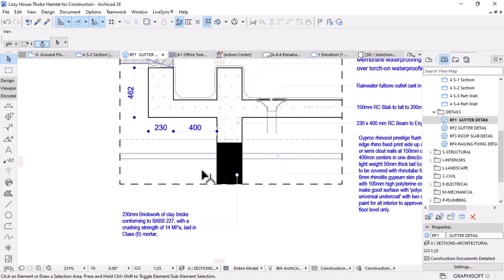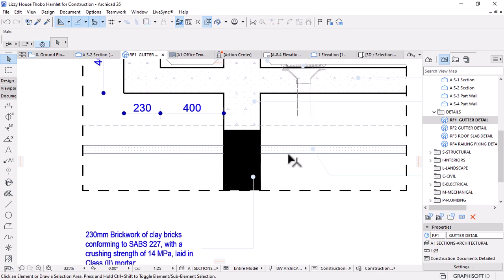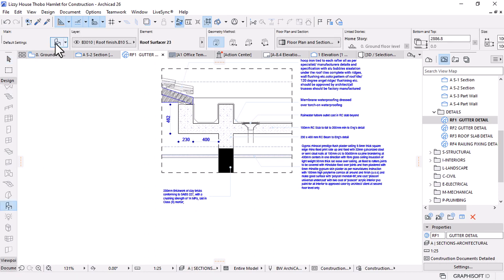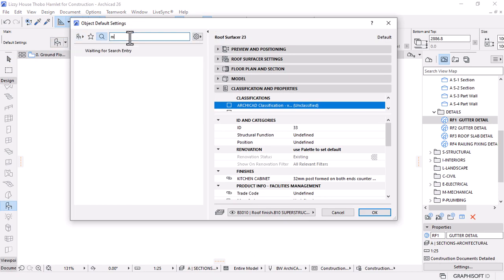I think we need also to place the ceiling cornice for this. Yeah, I don't know, do we still have that in our ArchiCAD? So let's go object. If you search for molding, if I'm not mistaken, there was a library from the previous versions for moldings. So let's see, maybe say mold.